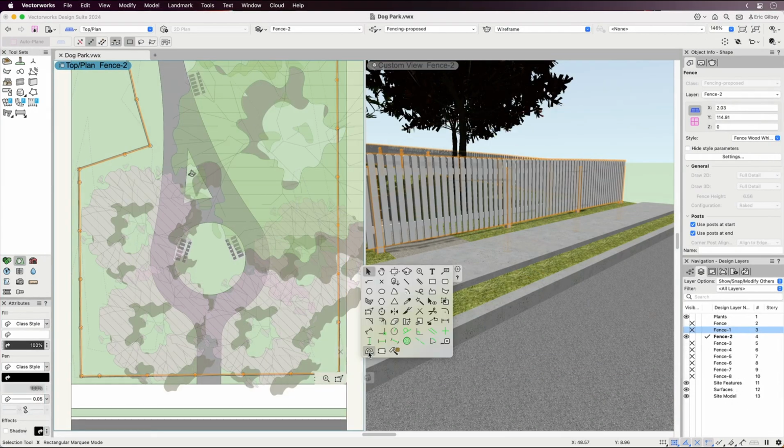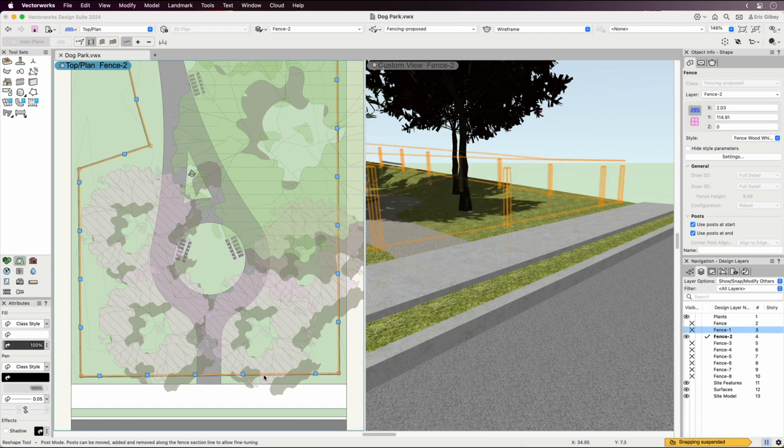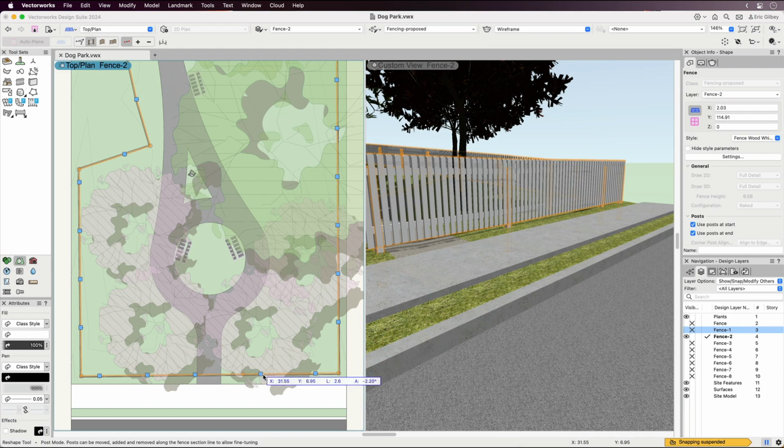And additionally, fence objects automatically facet to the designated post spacing when drawn in a curved path, which is a tremendous time-saving feature. Once you have initially placed your fence system, flexibly adjust or customize it using the familiar Reshape tool. For example, in order to accommodate an entryway, you can add, remove, and adjust the position of the posts to make way for a gate.